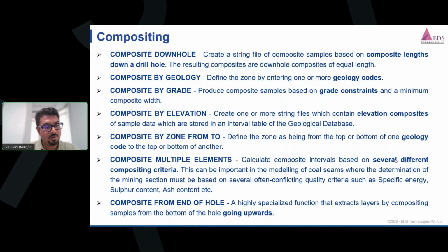Then another compositing method is from-to end of hole, so it is going upward. We start compositing from the bottom of the borehole and it goes upward. This is completely opposite of the downhole compositing. So these seven types of compositing we can handle through the Surpac software.